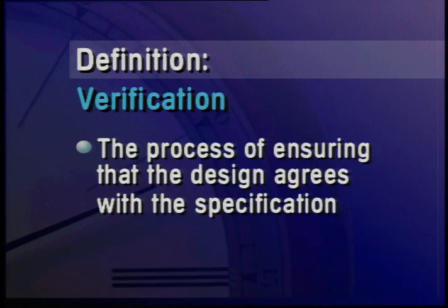One of the key steps in the top-down design methodology is the logic verification step, and that is the step we will be concerned with for the balance of this lecture. How do you determine that your design is correct before you proceed to the next step? Logic verification should occur as close to the actual design as possible. That way, verification is done at the same level of abstraction as the design. The designer needs to work with a single level of abstraction.